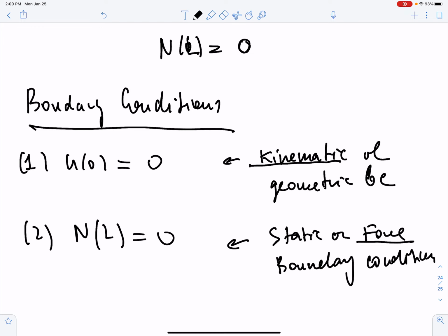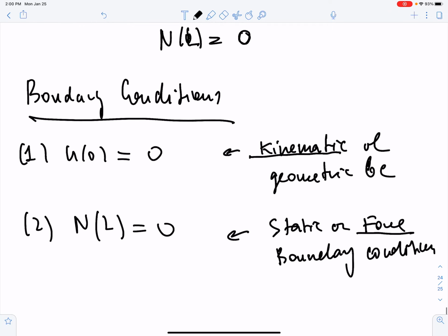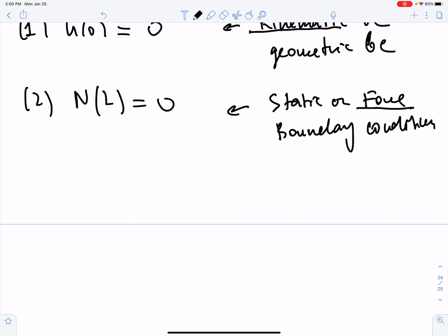And so an important remark here is that once you go to the boundary, in this case it's just a point, and at that point you need to decide what it is that you're going to apply. You can either apply kinematic or force boundary conditions. You cannot do both at a given location, because it could give you an ill-posed problem. So it's an important part.